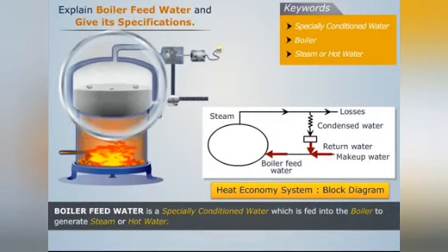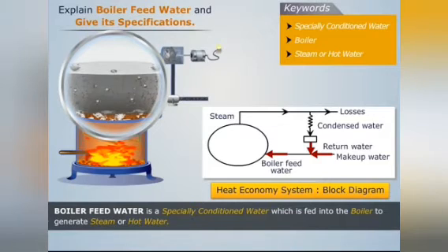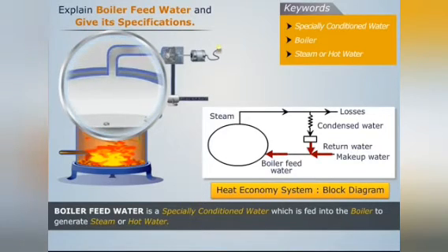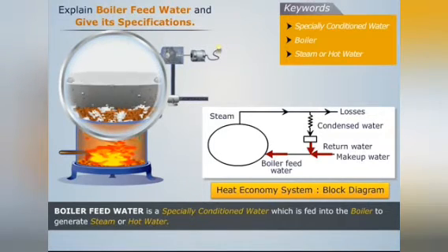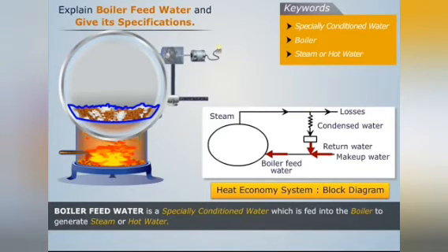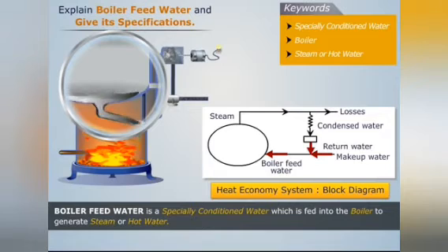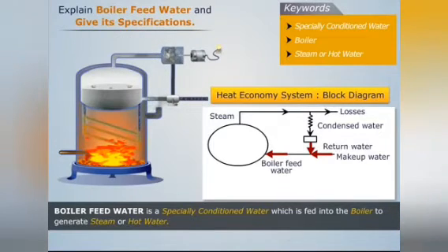Sometimes we see that some impurities settle down at the bottom of the boiler after the steam is produced. We know that steam which escapes from the boiler normally contains liquid droplets and gases. So the remaining water at the bottom of the boiler might pick up all the foreign matter from the water that was converted to steam. This results in the accumulation of impurities at the bottom of the boiler. These impurities can be removed by discharging some water from the boiler to the drain. Such process of blowing the impurities from the boiler to the drain is called blow-down operation.